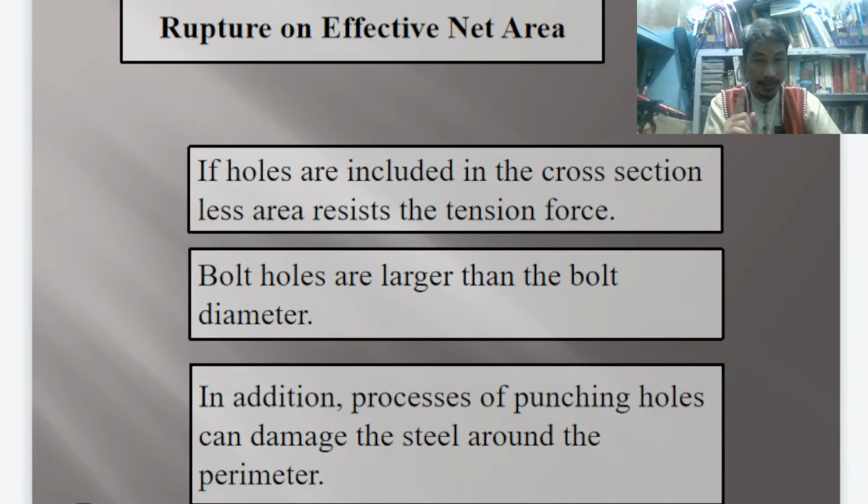It is being presented by the code because there is no mathematics in it. Another thing you can research about: if you can find another practical process that may give us a lesser amount of clearance from the diameter of the bolt, it is much better, because the greater the amount of net area, the greater its resistance capacity to failure.